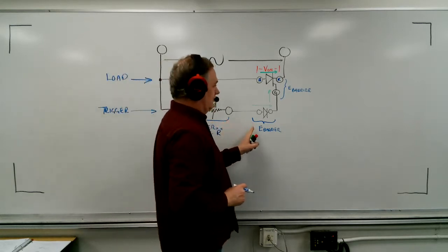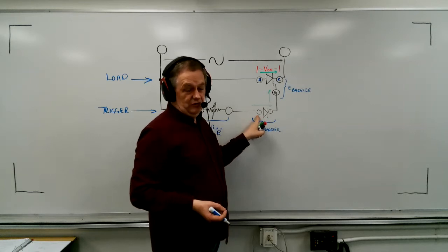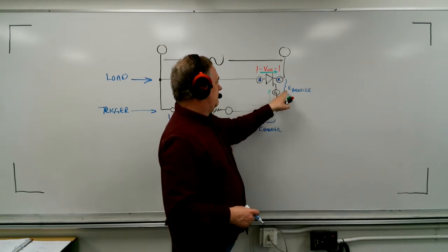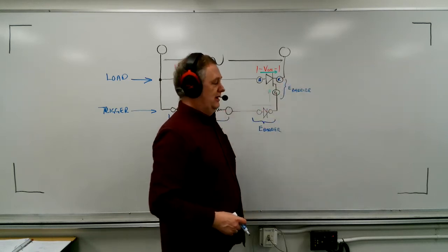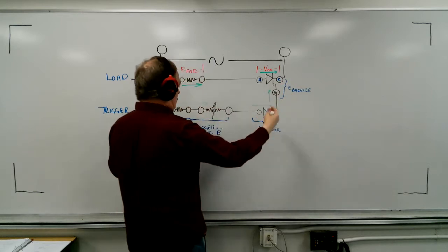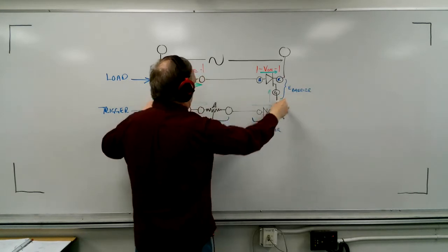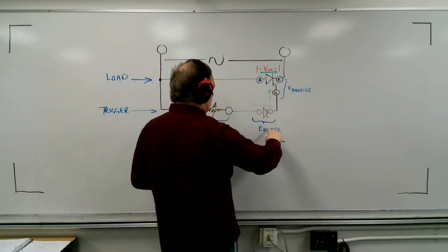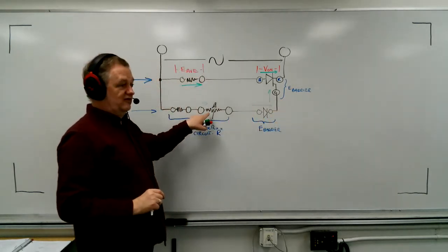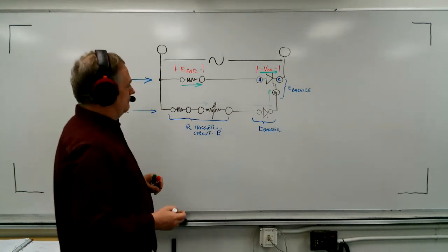And we have to make sure that we subtract this barrier voltage of the diode, if it's used, and this barrier voltage from the gate to the cathode. Those are going to be important numbers, and we need to realize that if I have a certain amount of voltage from here all the way across this, then these barrier voltages have to come off before I deal with actually calculating the resistance that we're going to have in this circuit. So that's an important part.